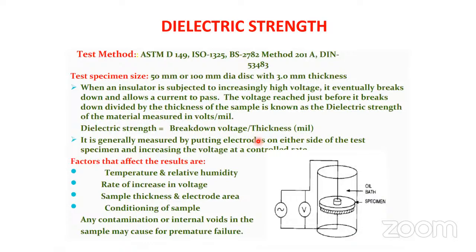Okay. Then what is the dielectric strength? Dielectric strength is when an insulator is subjected to increasingly higher voltage. Suppose some insulator is subjected to increasingly high voltage, it eventually breaks down and allows the current to pass through it. At the voltage at which the specimen breaks down, you can call it the